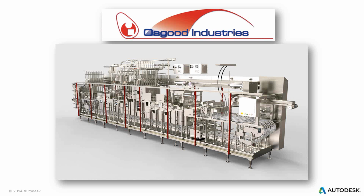And if you think about it from a thermal point of view, that can be pretty important because you need to keep your product in a certain temperature range. Yet at the same time, you need to elevate the temperature of the machinery periodically as you have to go and clean it, whether you're switching a product from one flavor to another, or it's just an end of shift cleaning or periodic cleaning dictated by the manufacturing process.